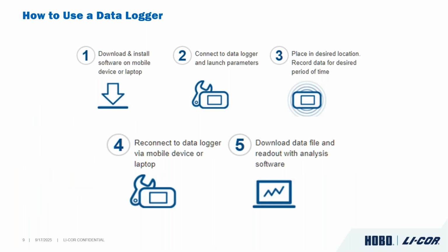Third, you'll go ahead and deploy that logger. You'll place it in the desired location and set it to record for your desired amount of time. Step 4 is when you're ready to collect that data: you will retrieve the data logger and connect it to the appropriate software. Then number 5, you'll download the data, and you'll be able to export it and read it out with the software analysis. So very easy, user-friendly, simple.